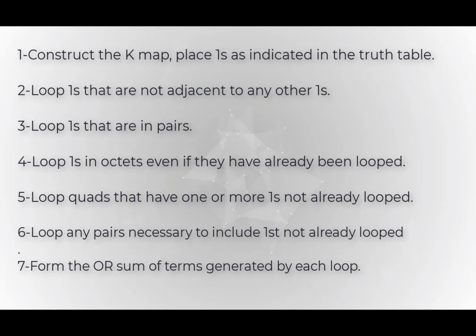Step 7. Form the OR sum of all the terms generated by each loop. Please be advised that when the largest possible groups have been looped, only the common terms are placed in the final expression. In addition to the grouping, looping may also be wrapped between top, bottom, and corners.